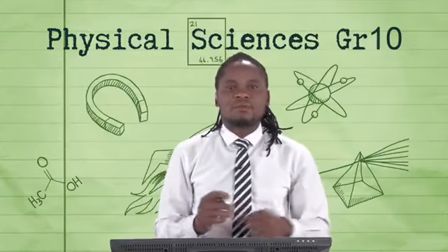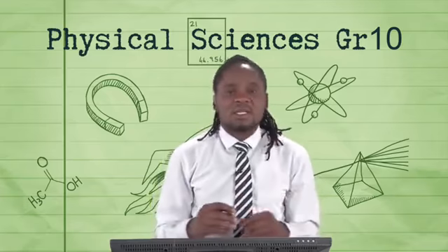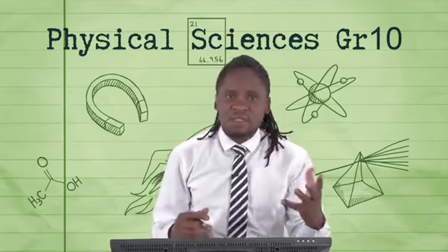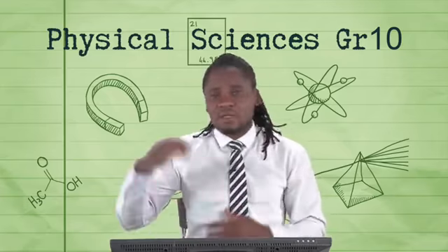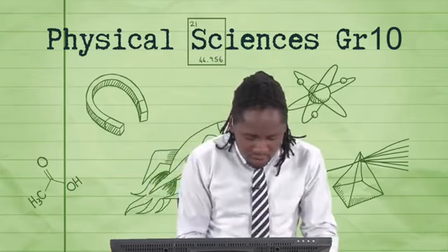Welcome back, guys, after our short break. Hopefully we're still having a good time as far as circuits. It can get a lot of calculations, but at the end of the day, it boils down to Ohm's law and understanding whether it's a series circuit, where current remains constant and V is divided, whereas if it's a parallel circuit, then we know that voltage across the parallel combination is constant, yet current is divided proportionally.